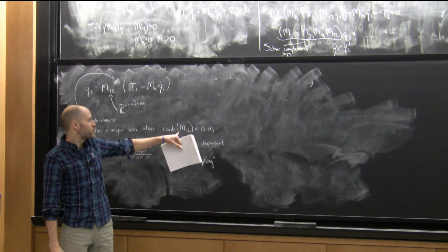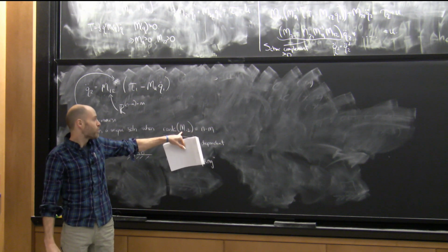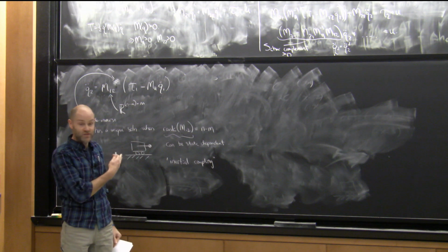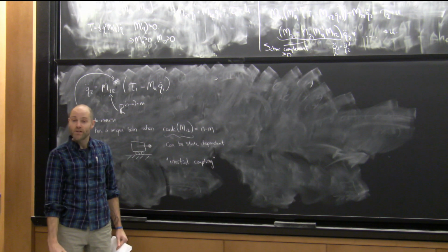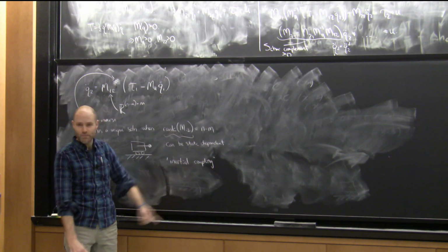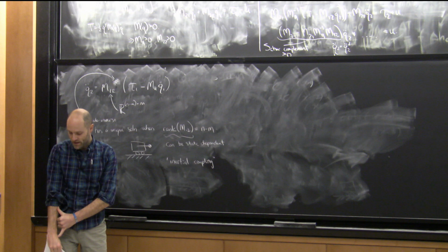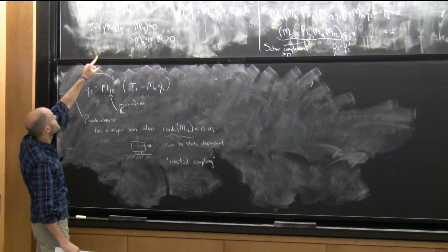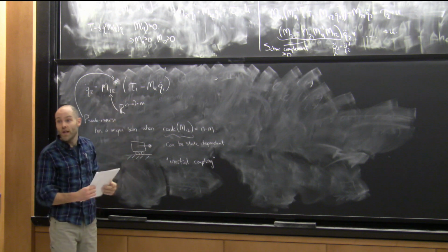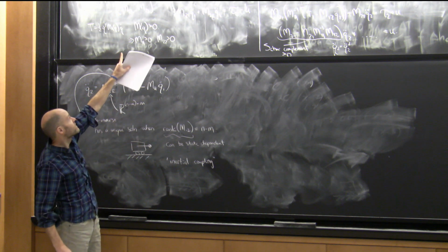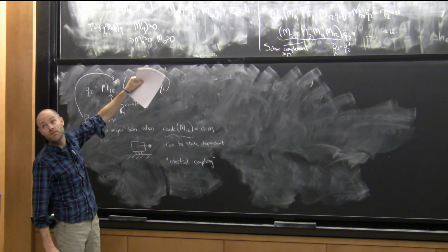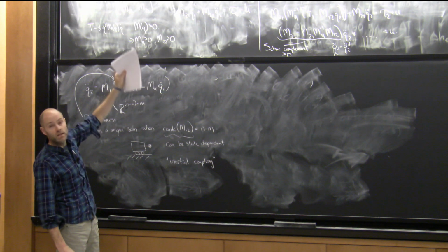If you run the numbers here for the Acrobot, then M12 is a matrix, well, it's a scalar in that case, where the number gets very small, depending on what's called inertial coupling. It really is the relationship in the diagonal matrix, the mass matrix here, right? It's the diagonal term. You'd like motion in the actuated joints to affect motion in the unactuated joints. It's got a very physical meaning.